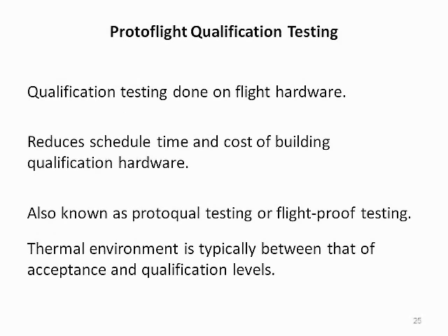Proto-Flight testing is a compromise in which qualification testing is also performed on flight hardware. It reduces the schedule time and the cost of building non-flight qualification hardware. This form of test is also known as proto-qual testing or flight-proof testing. The thermal test environment is typically between acceptance and qualification levels.